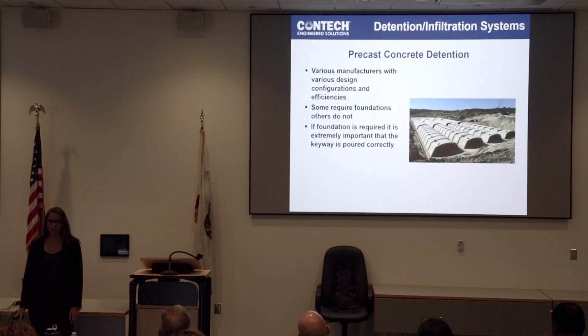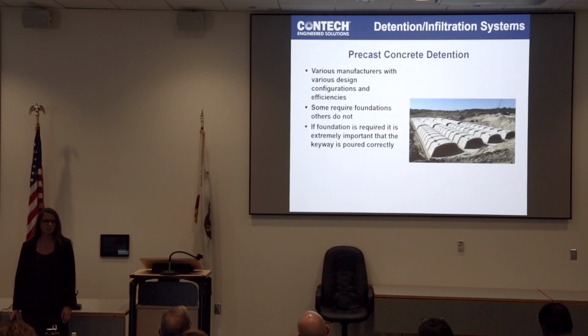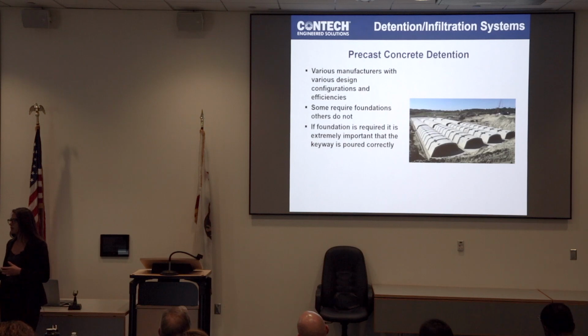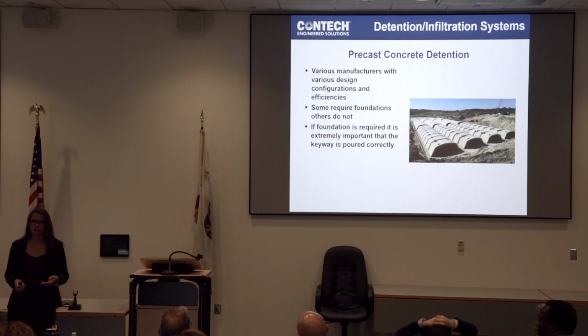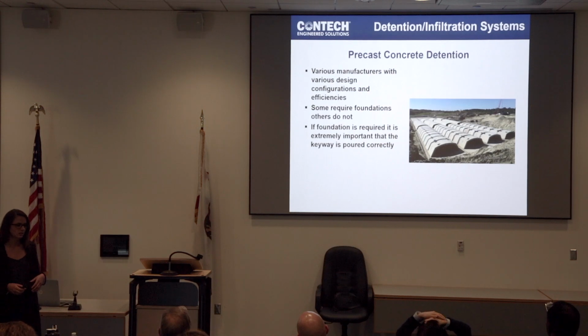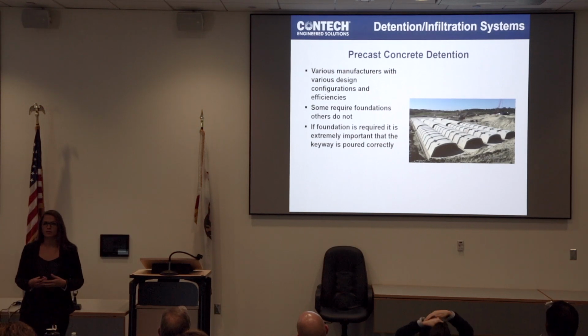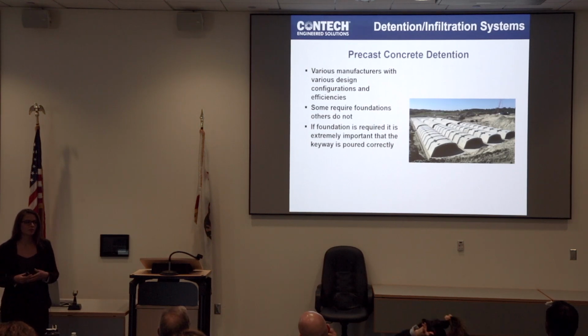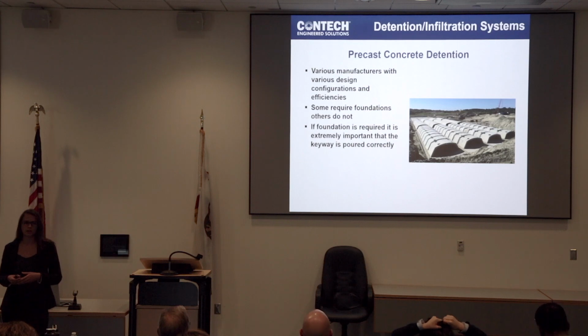Finally, precast or concrete detention for detention and infiltration systems. There's various manufacturers that offer these in various different designs and considerations. Again, it is very important that you take a look at your submittal drawings before you proceed. Also, some of them require foundations and other ones do not. When they do require a foundation, very important that the keyway is poured accurately.